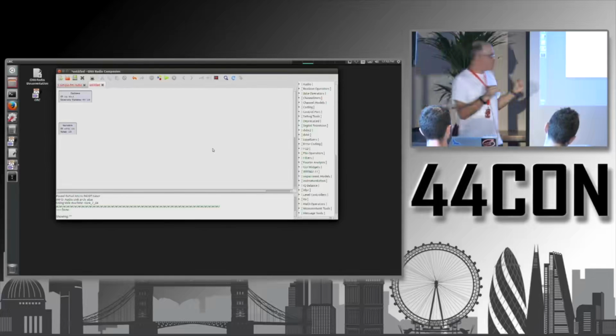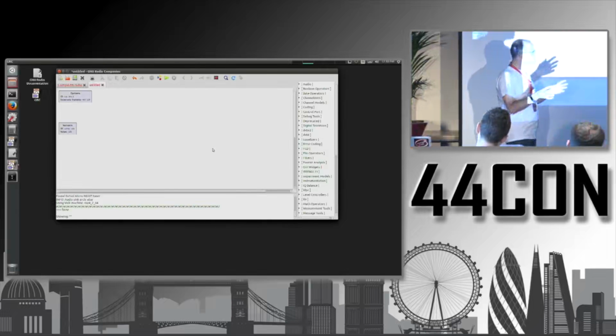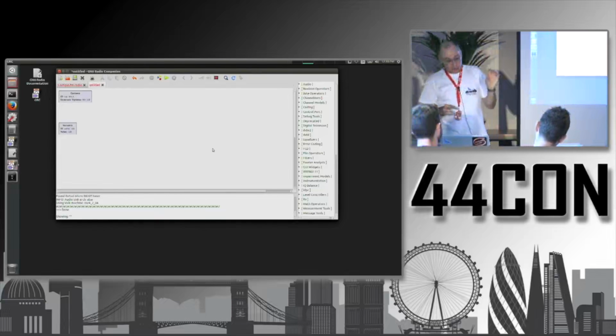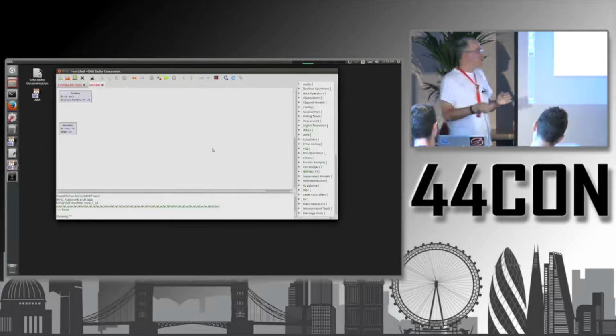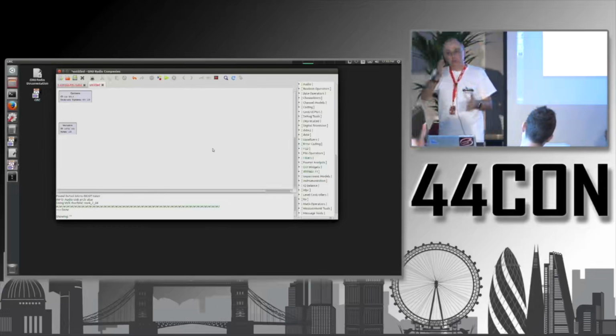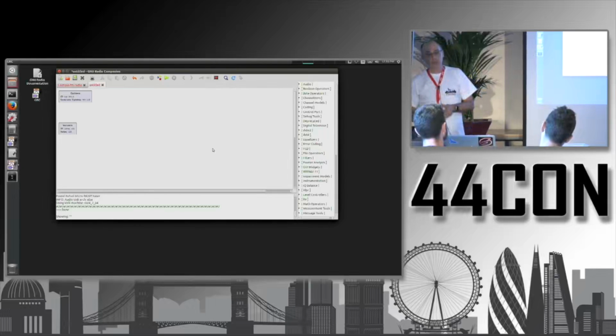So what we speak is about 300 to 3000 Hertz. That means that if we are talking about 300, the lowest frequencies, about 300 changes per second. If you would sample only once per second, that would not work because you have too many changes in the time you are waiting for your next sample.